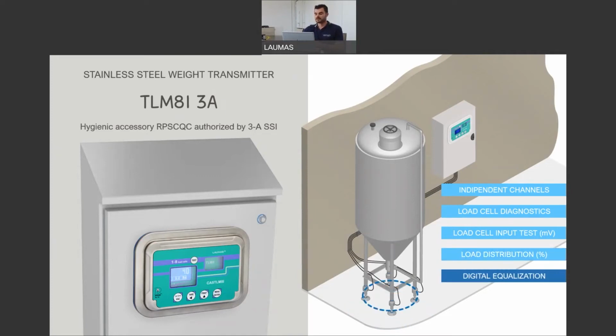Last but not least, during the first installation, you also have a very useful tool with our multi-channel transmitter, that is the digital equalization. So you will have the equalization of the 4 load cells done automatically by the multi-channel transmitter without using any trimmers.